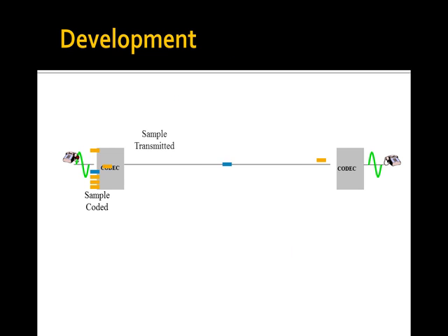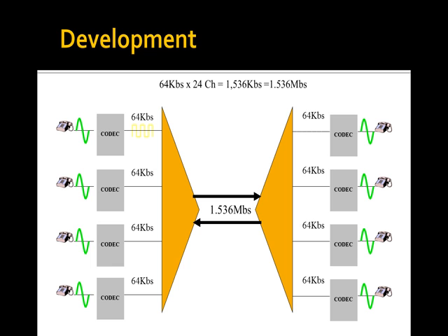Once we get our sample, you saw this one the other day. Once we get our sample, we take our bits, we code it, we send them across the link serially, we reconstruct that sample at the other end, and then we use an integrating circuit and turn it back into analog audio. We do that process that I just showed you 8,000 times a second. So we have to run that link in the middle at 64 kilobits. Since we're wanting to multiplex, what we're going to do is take one 8-bit sample from each of several channels and send it across the same link. We're just going to stack them up in order. So channel 1 sends 8 bits, channel 2 sends 8 bits, channel 3 sends 8 bits, and so forth. When we get to the end, in this case channel 24, we'll send 8 bits in channel 24, then we run back around and we start with channel 1 again.